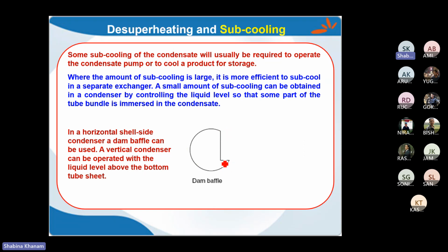So this is the vertical cut, and this type of structure we provide, and condensate up to this much height. Okay, up to this much condensate will remain there. Okay, otherwise we usually prepare a V notch over here. Okay, from this condensate should exit, but we are not doing that over here. If we require a little amount of subcooling, that is less than 25% of latent heat, okay, in that case condensate which is available above this, that will only be able to flow out.